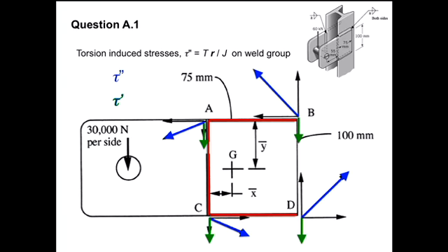Don't forget, I've tried to communicate that X and Y is okay for the setting up, but by and large, I'll be looking for you to think in terms of centroids, resultants, 2 force members and 3 force members, as per lecture and assignment work. So you can quickly get to saying, okay, we've got a radius there, and that force vector in blue is going to be normal to that radius. That's the kind of insight I hope everyone in the room will present for me in the exam.